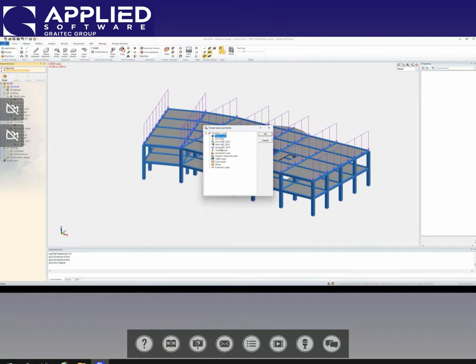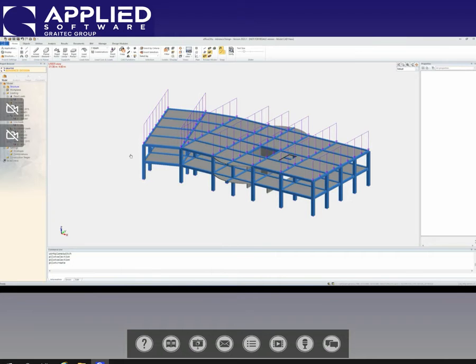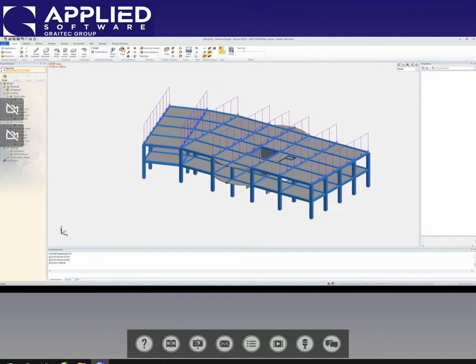And we also have other types of loads like dynamic loads, crane loads, pushover, etc. For this project, I will just keep my dead loads here. So you can just go on and delete the other ones. You just right click on the load and you can delete them.